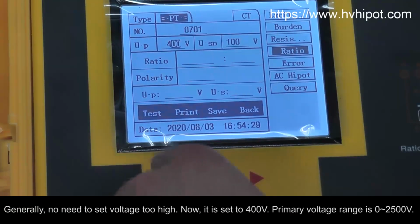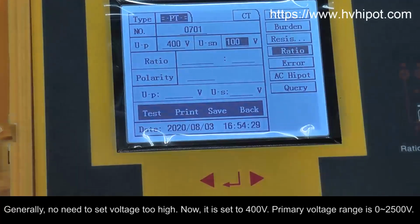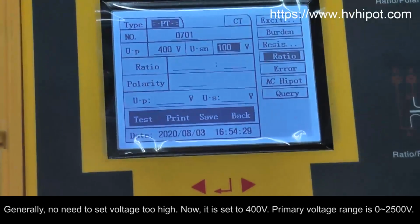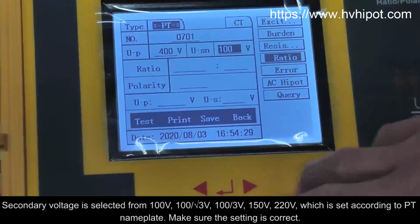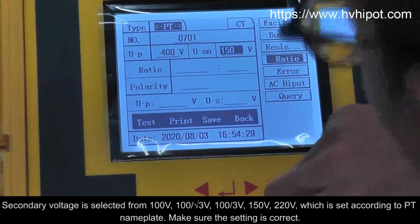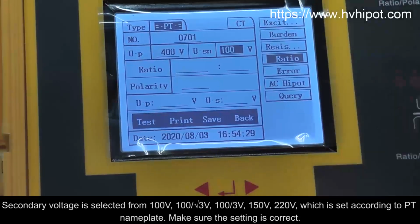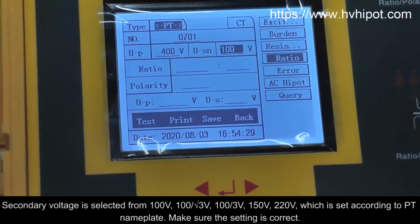Generally, no need to set voltage too high. Now it is set to 400 volts. Primary voltage range is 0 to 2500 volts. Secondary voltage is selected from 100 volts, 100 over square root 3 volts, 100 thirds of a volt, 150 volts, 220 volts, which is set according to PT nameplate. Make sure the setting is correct.